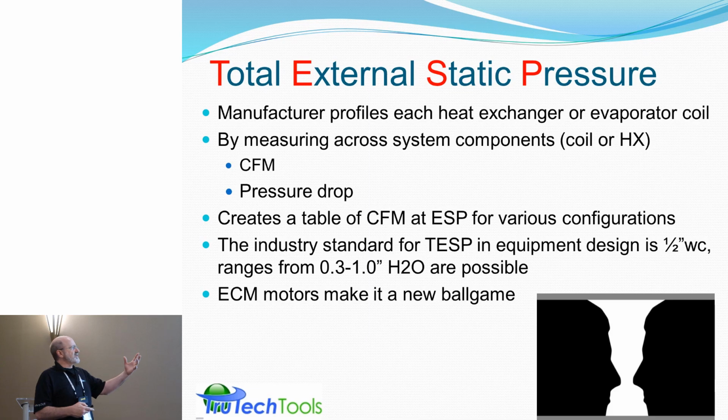So this total external static pressure, the manufacturer actually profiles the heat exchanger or the evaporator coil. They'll use another device to measure the CFM, probably a lab grade device, and run it up through all kinds of speeds that their equipment normally runs through, and then measure that pressure drop with a precision manometer and develop a table of values that you can then take in the field and use.